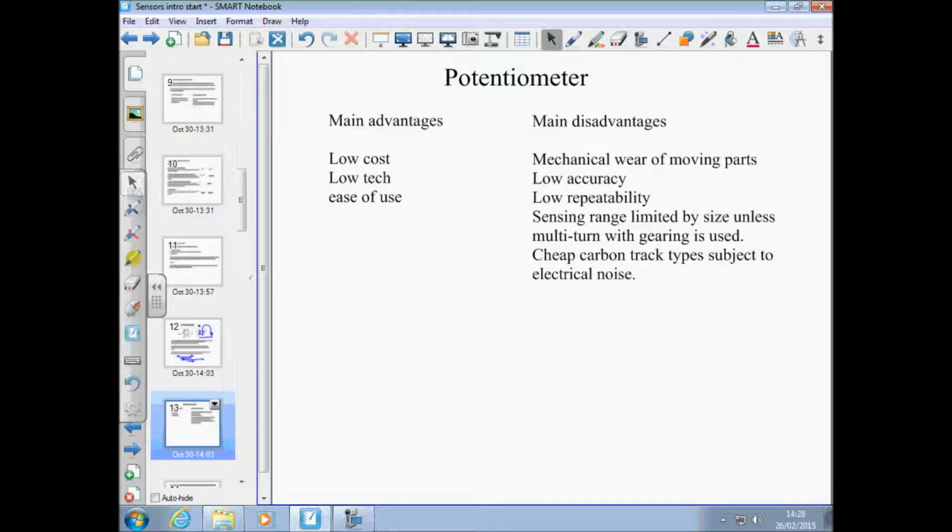We have the linear ones, and that's like a hydraulic cylinder. That's almost lifting a stainless flap up on the top of it, and you would get grease and oil ingress into that, and that would cause loads of issues as well. But you know, it just depends on the application which type you pick. But they're okay as long as absolute repeatability and accuracy is not an issue.